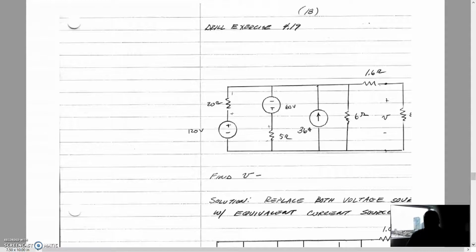source transformation. So in this case, we have a fairly large circuit, a big collection of voltage supplies, current supplies, and resistors. Of course, like every other circuit in the Nielsen book, this makes actually no sense in practice. And we have this 8 ohm resistor over here, and our question is, what's the voltage across this resistor? And again, that's a critical part about source transformations: we're looking for one unknown in the circuit, in this case, the voltage across one resistor.